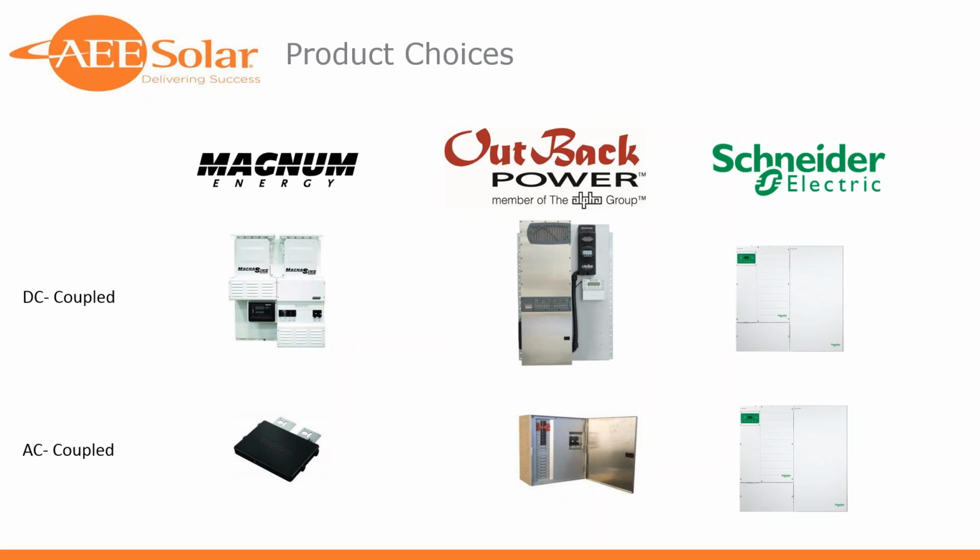So you're limited to pretty low kW coming out of that inverter to support loads in backup. I believe they've raised it to 5 kW, but there's very little surge capability in backup mode to support startup loads or turning motors. So it's a bit apples and oranges when you compare something like a Magnum, an Outback or a Schneider. Having an onboard transformer, those are going to provide a lot more surge or peak power than a SolarEdge will.